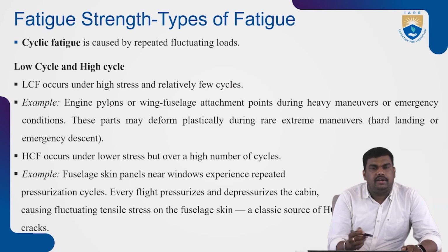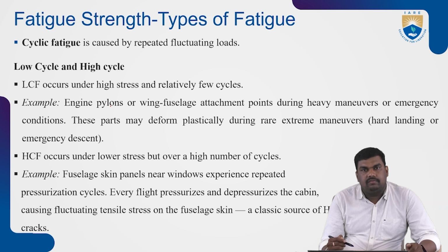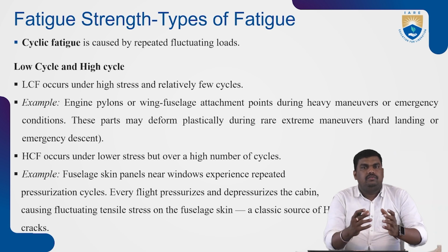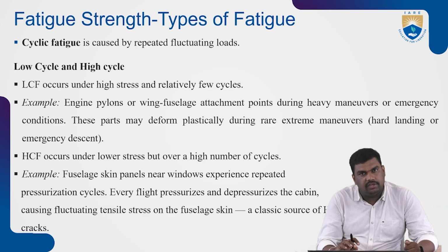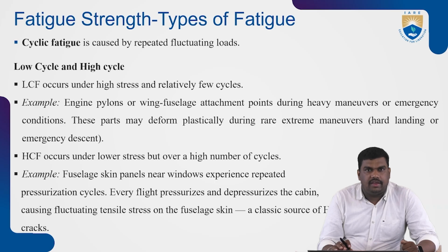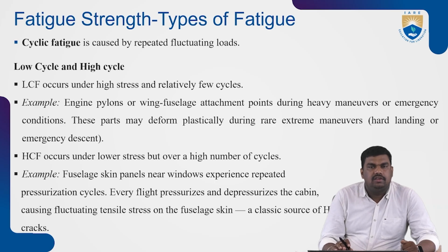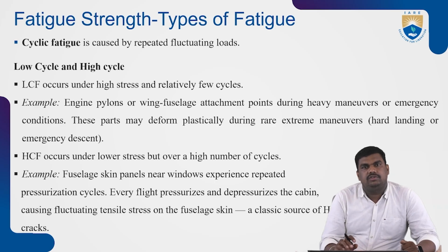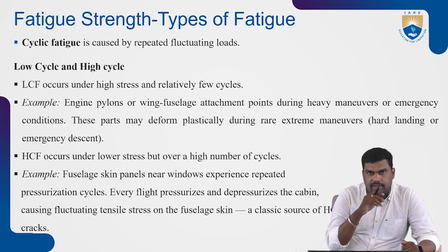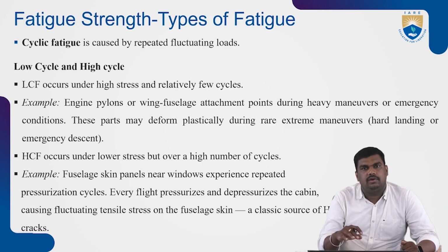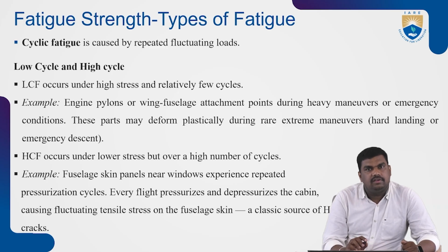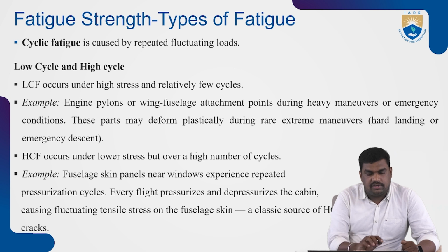For example, the panels where you are attaching the wing to the fuselage. There you will experience high loads due to all the maneuvering conditions. The wing will experience high stress. So the area where the wing attaches to the fuselage will experience that high load. Each and every time during takeoff and landing, this reverses, so one cyclic stress happens each time. So high stress leads to low cycle fatigue.